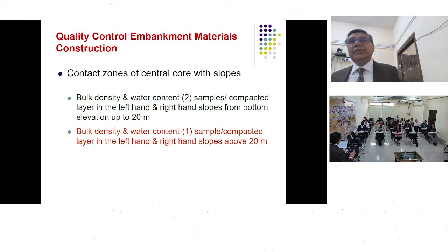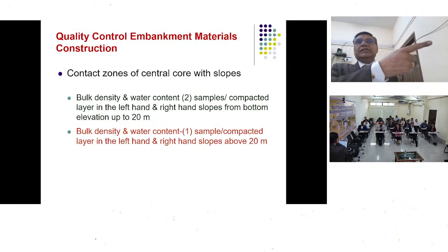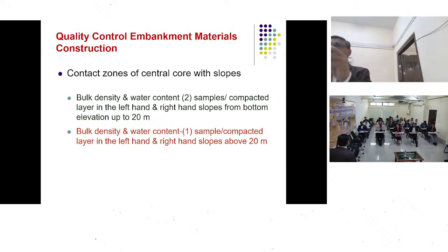So we immediately said, okay, you stop. Please talk to the design team and the construction team, and evolve a procedure. Maybe if it is not possible, use bentonite at least, because ultimately we require a more impermeable layer. Those are cables, those are zones of weakness. Compaction cannot be done to the maximum extent there because it may damage the cable. So you need to provide a material which is more flowable and more impermeable to surround those cable regions.